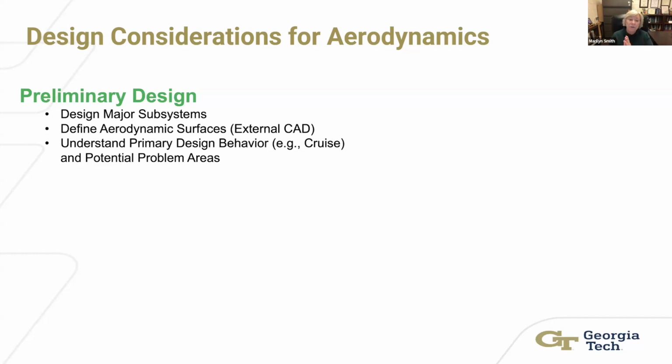Now, here you also will develop your external CAD. You need to look at all of your aerodynamic surfaces, including control surfaces at this point. You want to understand your primary design behavior, okay? Cruise, can you meet your performance goals? This is where you drill down and you use something higher fidelity aerodynamic-wise to make sure that your lift and drag gives you the long-term cruise you need.